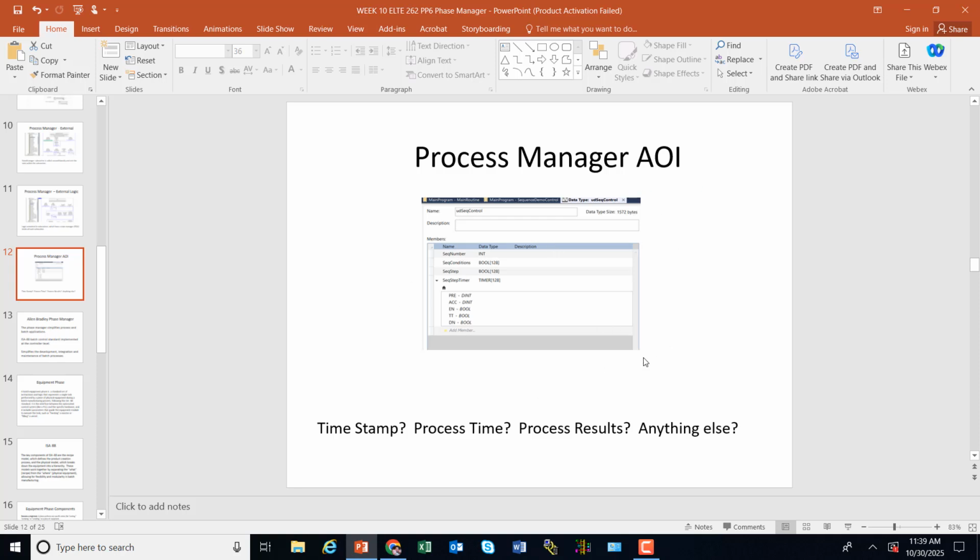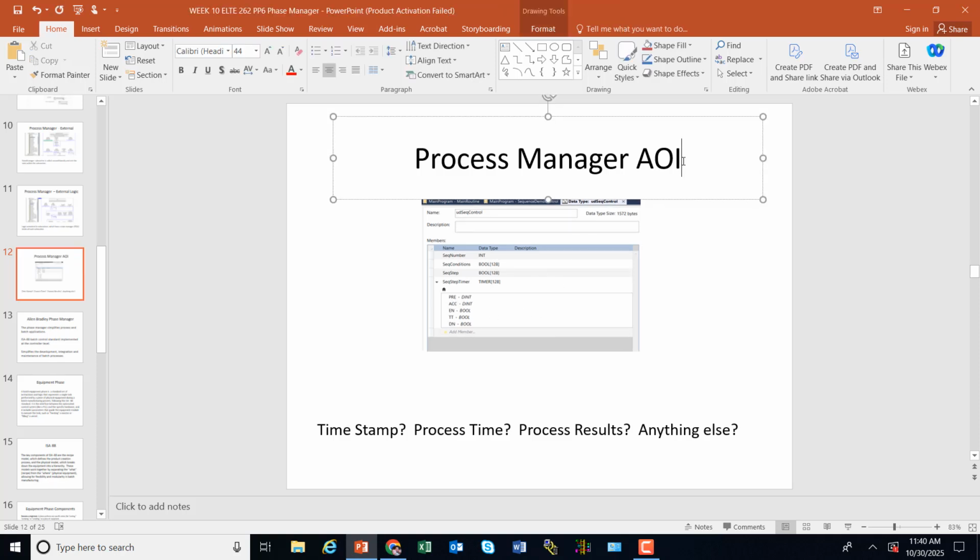In the process manager, I created a little AOI here. In my tag here, I could put the step timer, and I could have a variety of step timers. I've got a little array here in my sequence, in my conditions, and that's, I think, what many of you develop. So when you're managing your process or your sequence manager, it's best to have a user-defined tag here, right? You could do an add-on instruction. I think I'll show you that later. But this might be a user-defined tag that's got the stuff that you need in here, to control and watch and advance all your steps and everything like that.